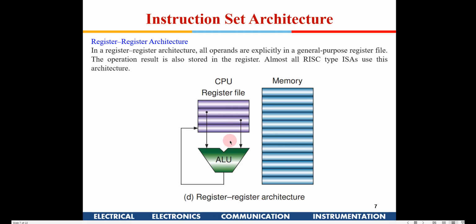Pipelining is very easy for that, and that is the reason when you have so many cores running in parallel, they are all actually small RISC processors, and whatever CISC instruction you give is decoded into small RISC instructions within the CPU. So from the top level you could call it a CISC CPU because it accepts CISC instructions, but practically modern day CISC processors use small RISC cores.